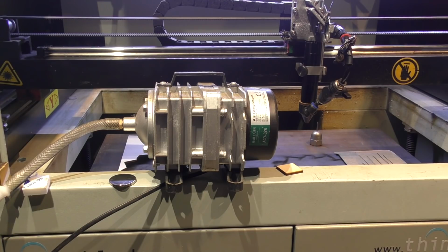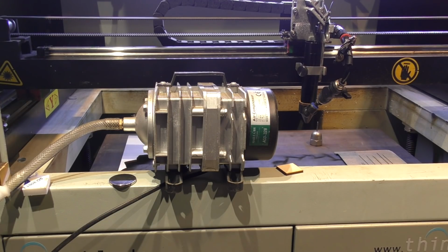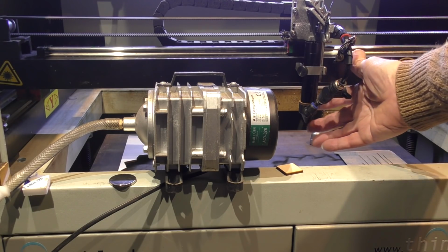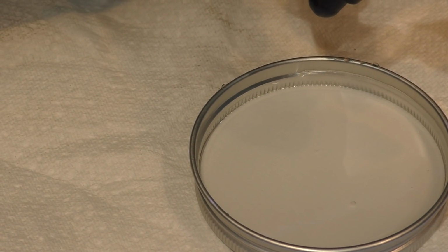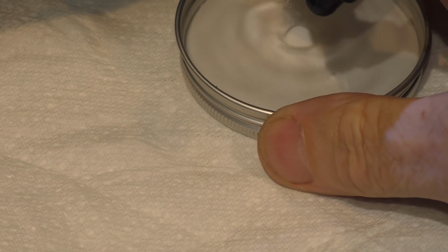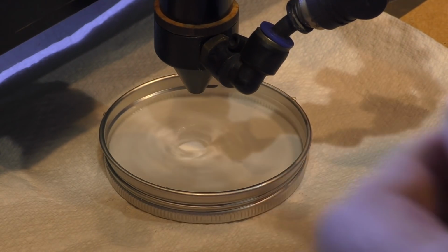Pressure across an orifice develops a flow rate. The bigger the pressure difference across an orifice, the more flow I will be able to deliver across that orifice. If I leave this ball valve set exactly like it is and I increase the pressure in the system, I will increase the flow rate through the nozzle. So look, I've increased the flow rate to 5 litres a minute. What's it done to my flow pattern? As you can see, I still have got a fairly stable flow pattern.